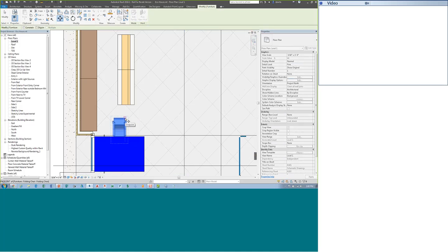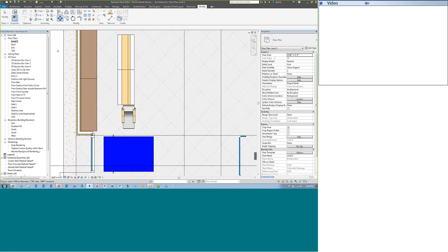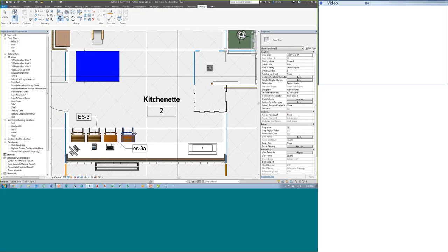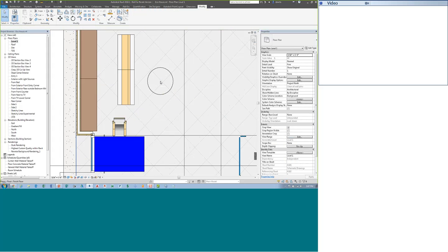They may use the snaps to pick a point and then move it somewhere else to be another snap point, or they will take the move command, let's pick something else because those are aligned to each other, and they'll just click wherever they want and move it in the direction that they want, and they'll type in a distance, say 5 for 5 feet, and hit Enter, and it moves in that direction. That's a pretty typical approach for using the move command.